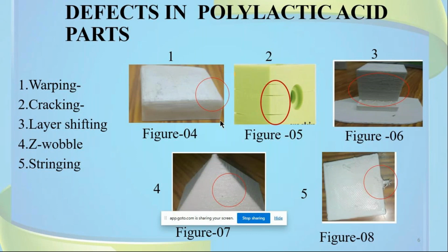Warping in 3D printing shows up mainly in large parts. The thermal stresses in the part become more powerful and end up pulling the part off at the corners. PLA is, as you know, the material with the least warping in 3D printing, because it has the lowest thermal expansion coefficient of all. So when PLA parts cool, they shrink less than other materials.